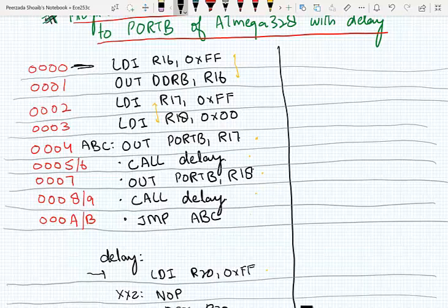So it expects the first instruction at memory location 0. So how do we direct our compiler to put the opcode of the first instruction at memory location 0? What we do is use an assembler directive, that's a pseudo instruction. We direct the assembler where to store the first instruction, that is .org.